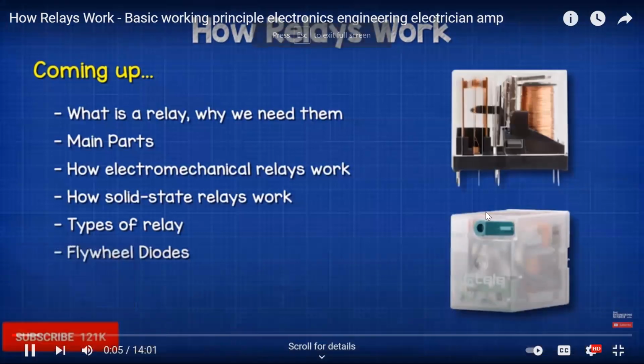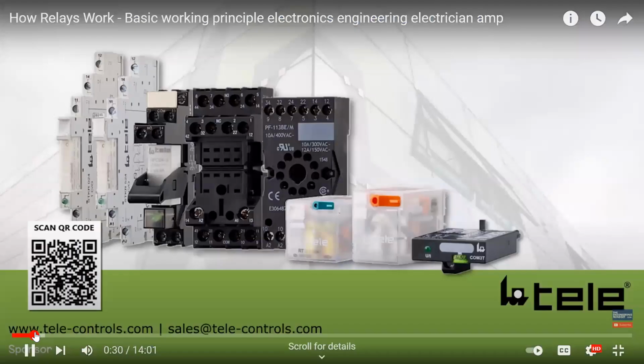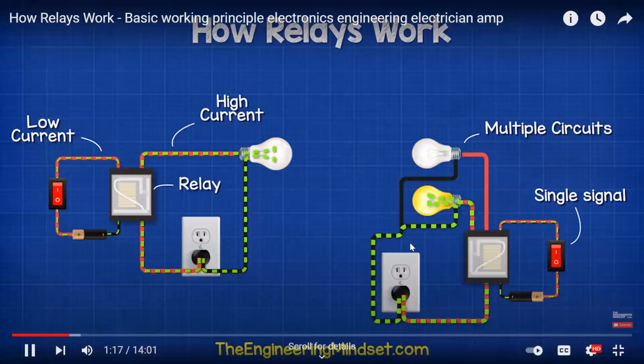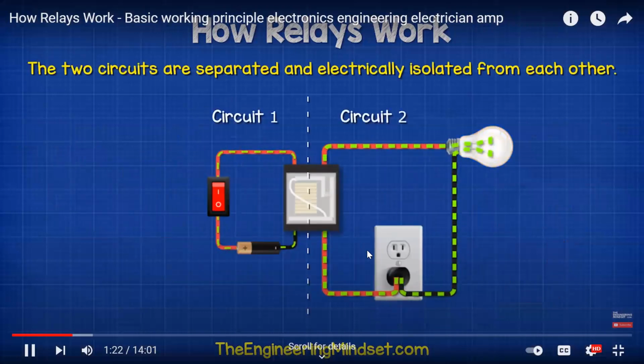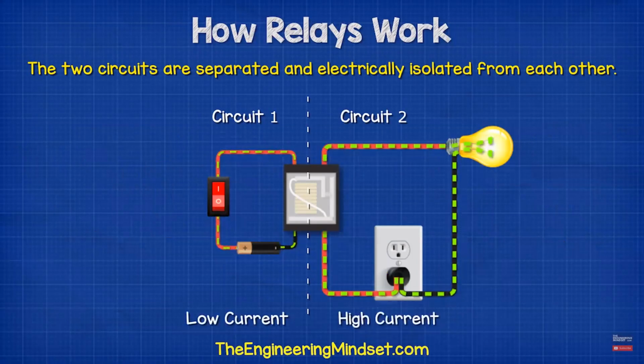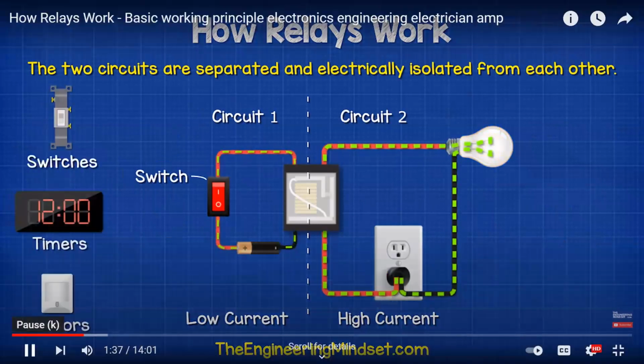Hey there, guys. Relays are used so that a larger switching load may be controlled by one signal. A relay ensures complete electrical isolation between the controller and the control circuit. Relays are often used in circuits to reduce the current that flows through the primary control switch, a relatively low amperage switch, timer, or sensor.